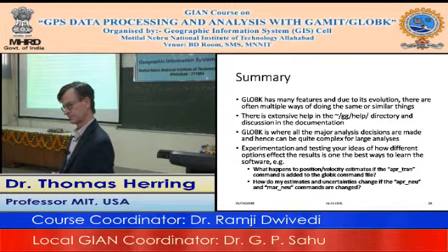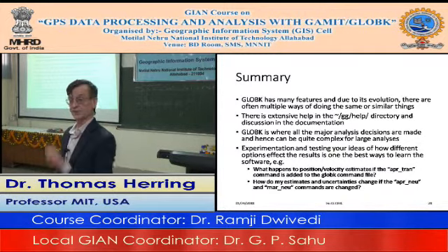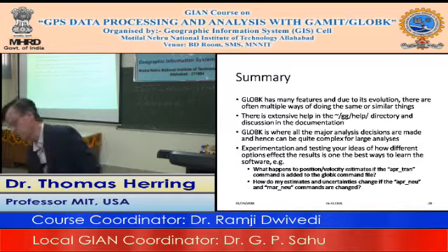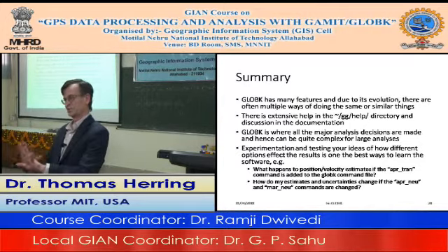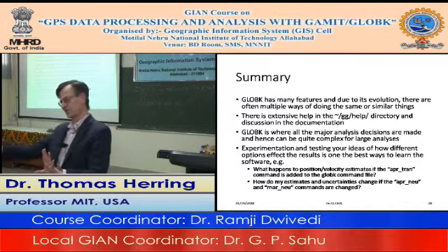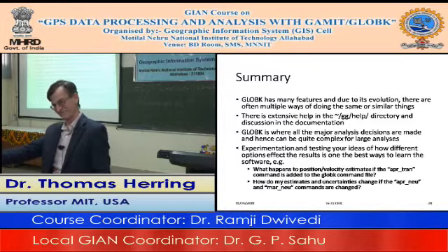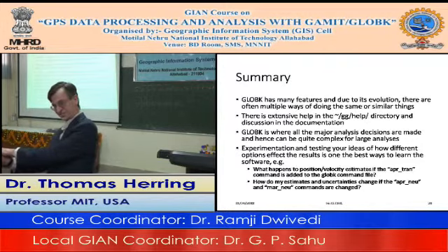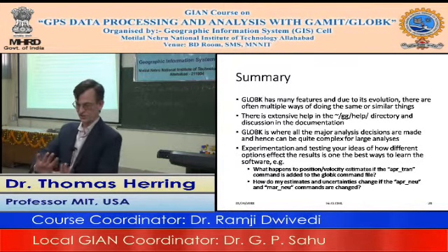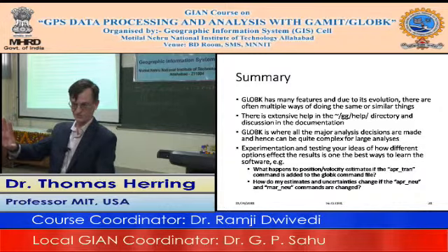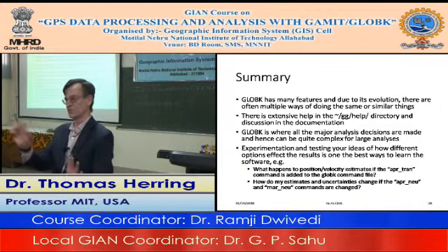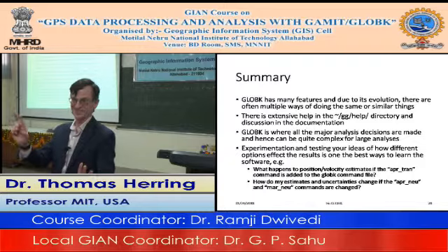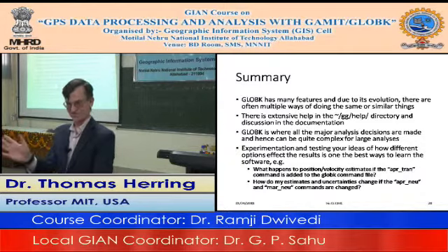Similarly, what program can we use to estimate the velocity? TS-FIT. There are a couple of ways you can do different reference frames. You could use TS-CON to rotate the time series into the new reference frame, and then use those new time series in TS-FIT to get the velocities. Or you could fit the velocities in the original reference frame, and then use a program called VELROT, which will rotate them into a different one.